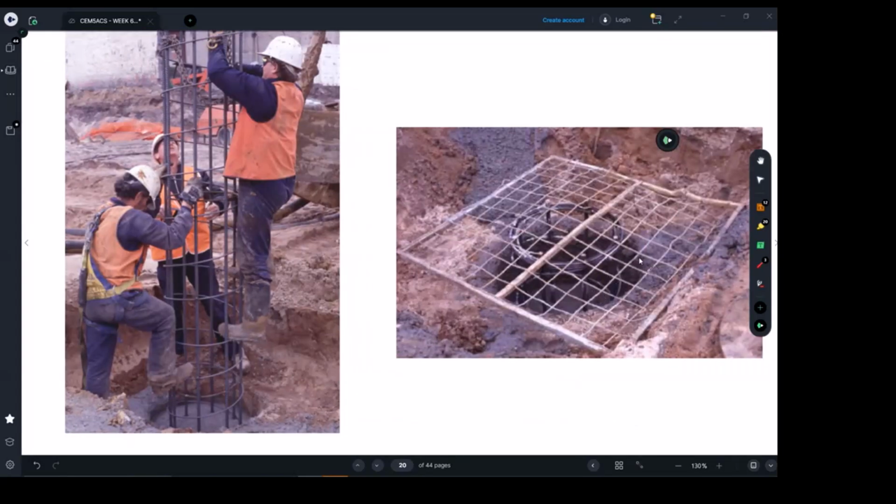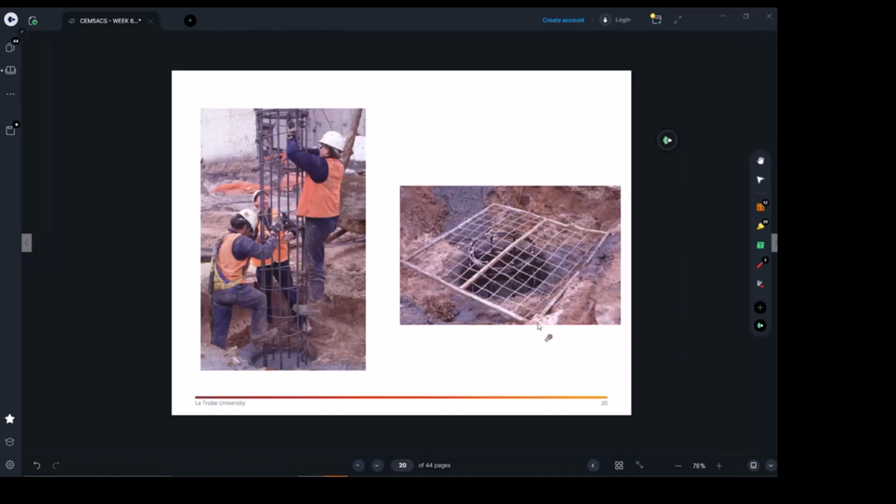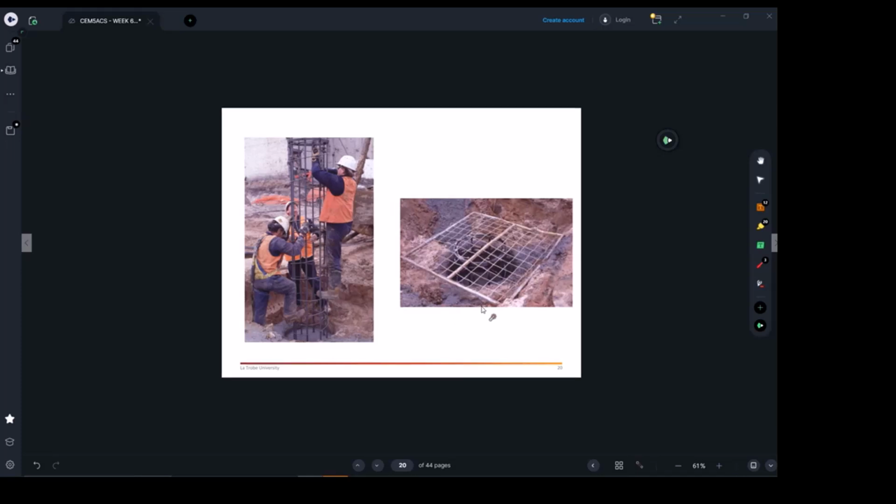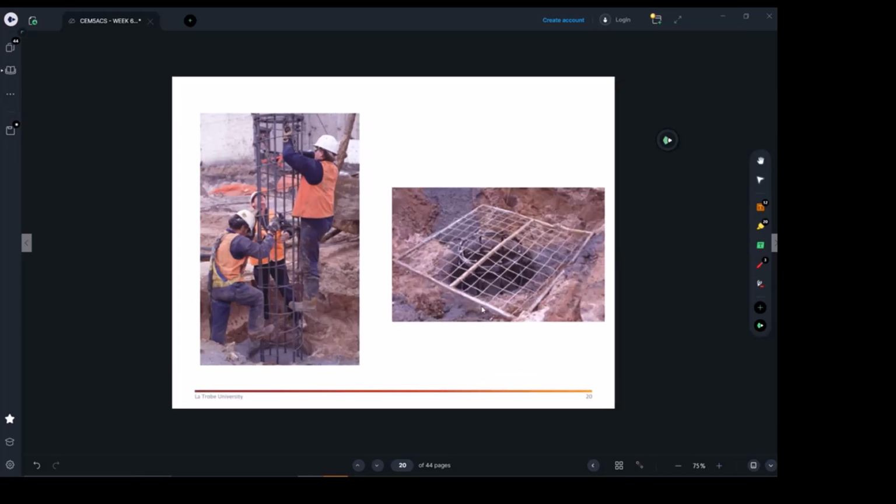We're saying you always need to keep room for the pile cap. So there should be room for the cap, because when you're done within a few weeks, when all the piles are placed in position, you will come and start placing your pile cap, whether it is for a retention system we talked about last week or for a tower, a building we talked about.